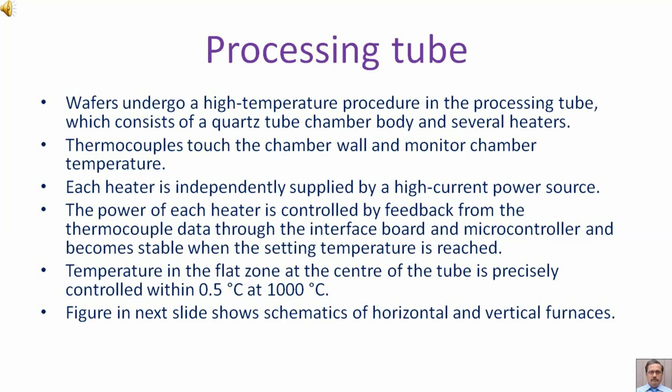Each heater is independently supplied by a high current power source. The power of each heater is controlled by feedback from the thermocouple data through the interface board and microcontroller, and becomes stable when the setting temperature is reached.